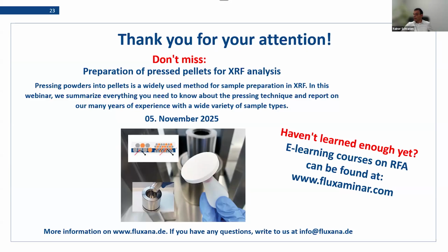There's another question, can this be used for portable XRF? Portable XRF, I made the experience that they are very stable. So there's probably no drift correction really necessary. But this you can check with your manufacturer, because, for example, on our portable XRF, we have a control sample. We measure on a regular basis. And as long as this is always good, you don't need to do any drift correction.